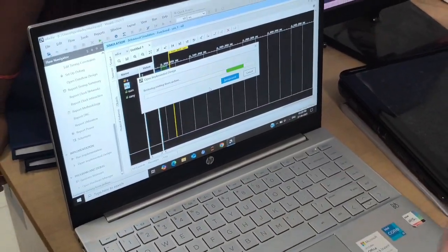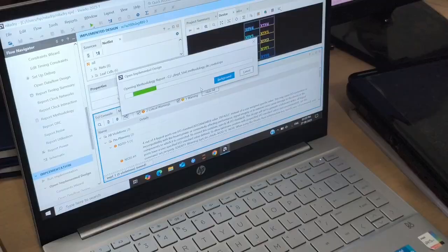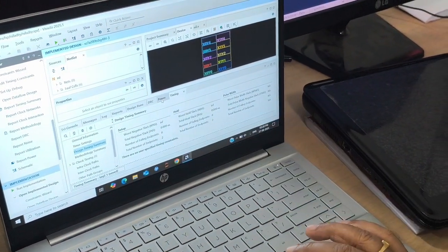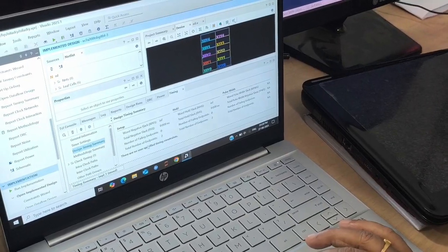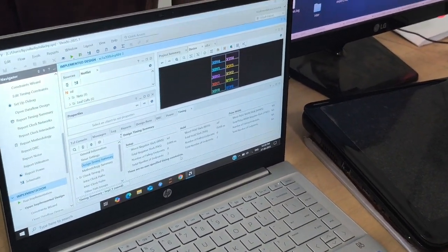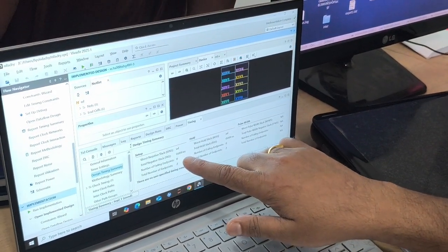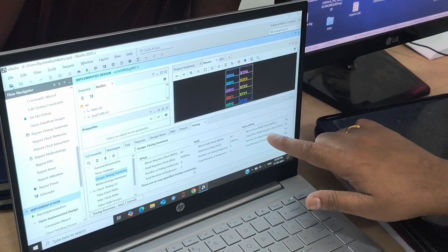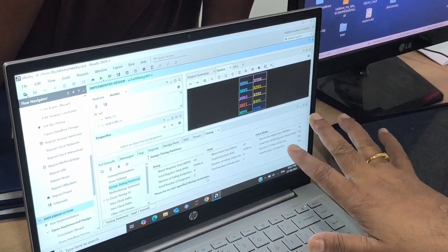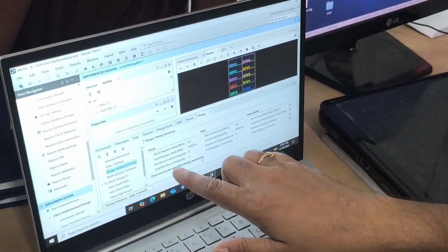So now timing information will come. In the report you can see the timing reports now. See here the worst negative slack is infinity, so there are no user-specified timing constraints. I did not give any constraint at the beginning, I told you. Without the constraint, this is the total negative slack, this is the hold slack, and these are not applicable because I did not give any timing constraint. Now I will tell you how to give the timing constraint.